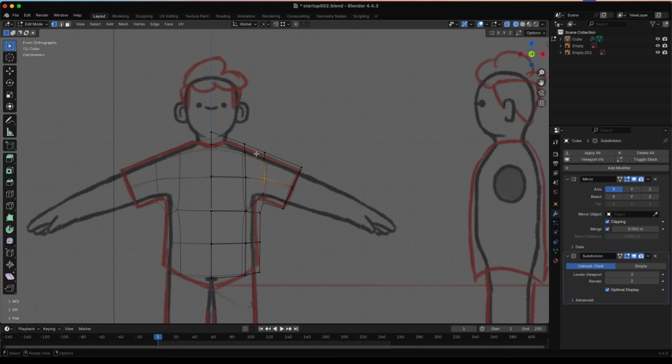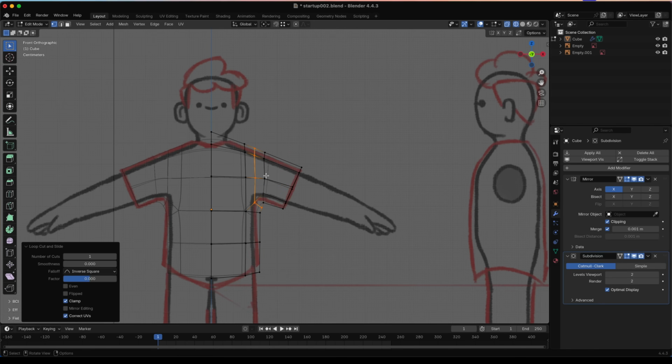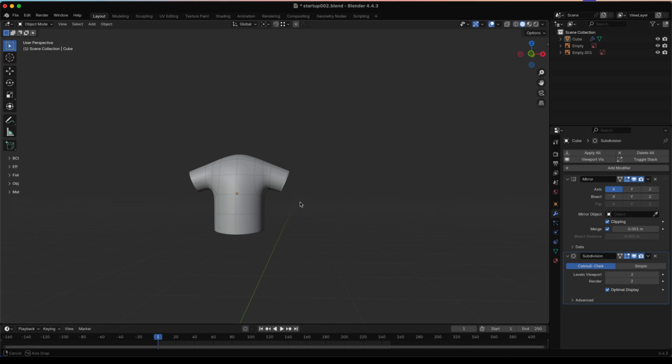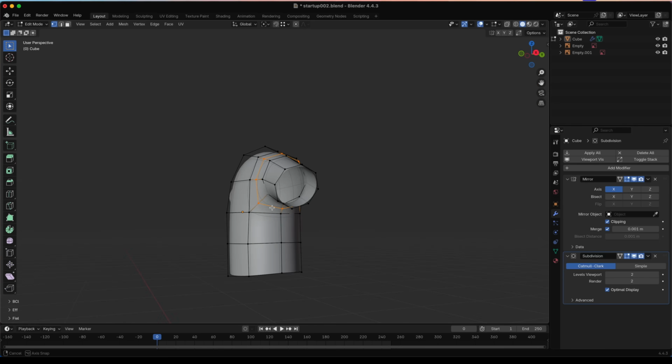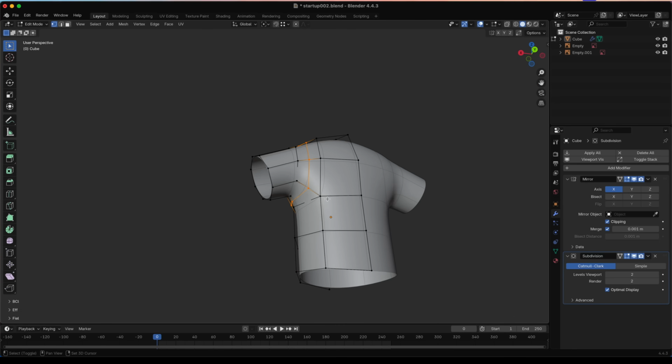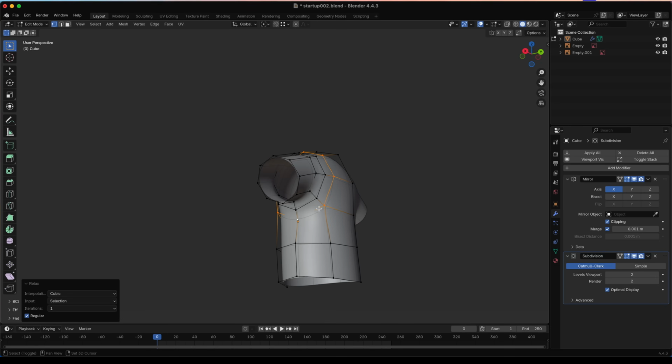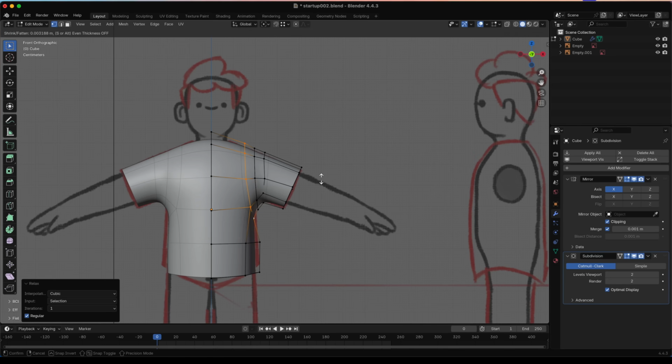So let's add in another edge loop with Command R. We're going to put it right there, and adding more geometry there will actually tighten the armpit up a little bit, and will make it a little bit less barrel-chested and jacked. So as you can see, there's some awkward, inorganic angles there. So we're going to hit Shift R with that. Then let's select this edge loop here, and we will Shift R there as well.